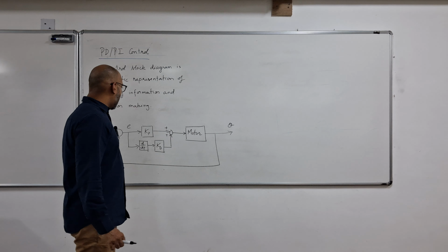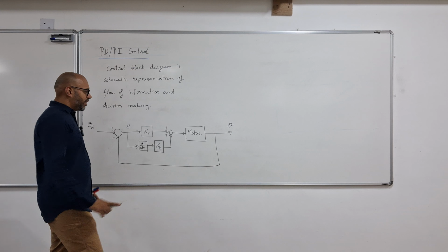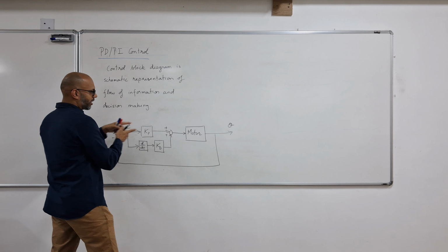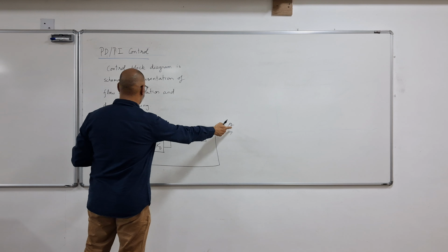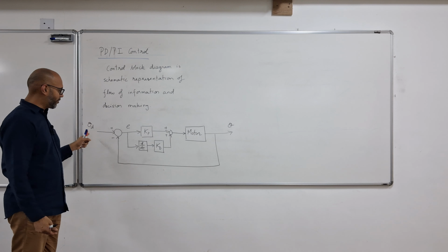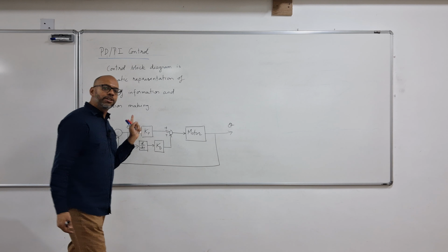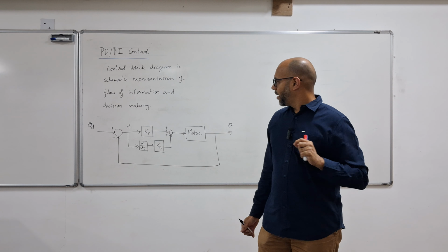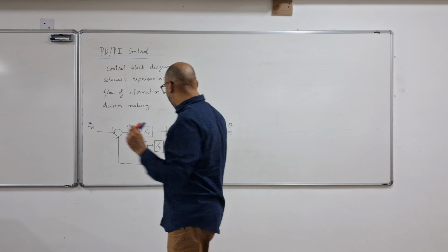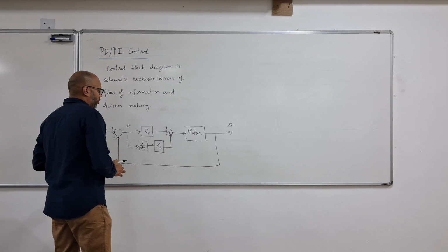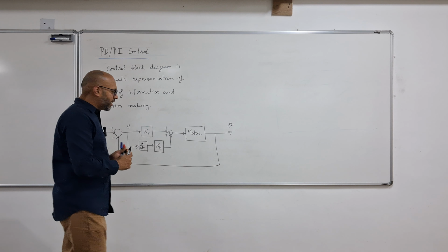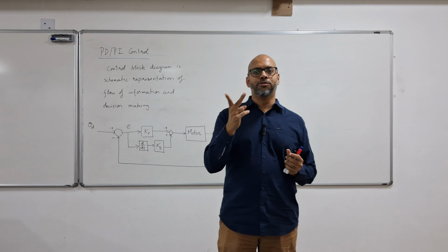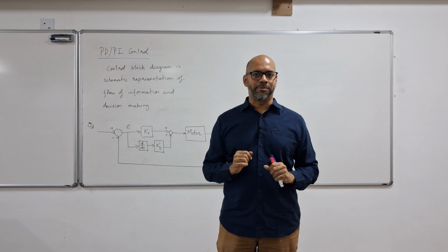the motor. And once you put all of this together, this is called a feedback loop, and this helps ensure that the motor is always achieving an angle that you wanted to achieve in the first place. And it's up to the user to choose both of these gains, kp and kd. Having drawn this, now let's think about this a little bit more. What this is really doing is taking corrective actions based on two different pieces of information.